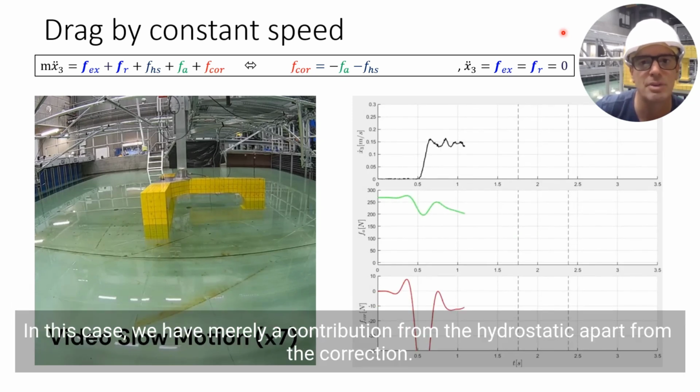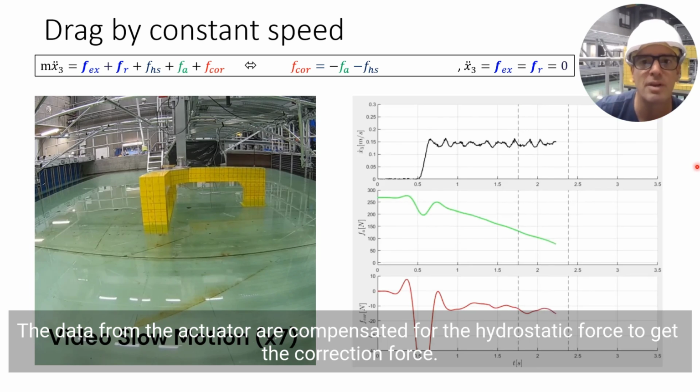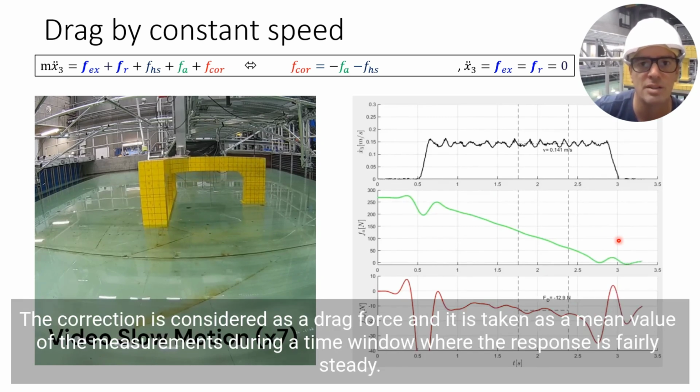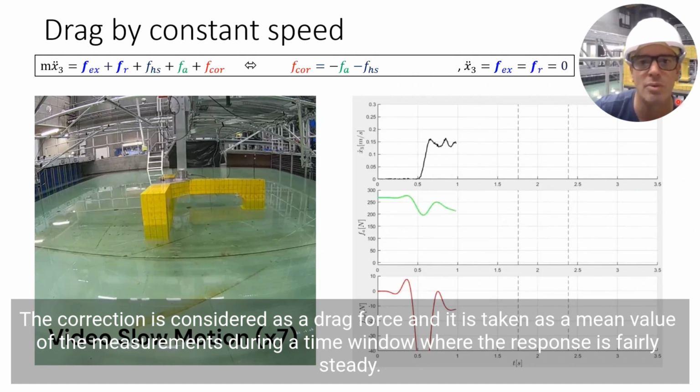In this case, we have merely a contribution from the hydrostatic apart from the correction. The data from the actuator are compensated for the hydrostatic force to get the correction force. The correction is considered as a drag force, and it is taken as a mean value of the measurements during a time window where the response is fairly steady.